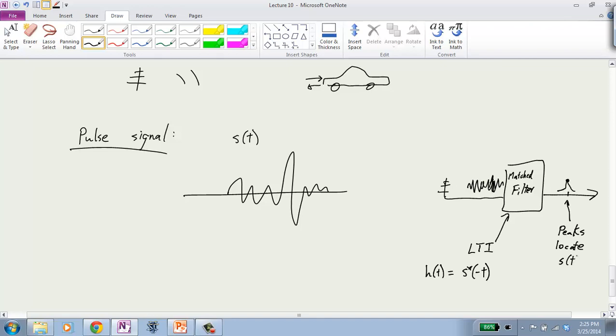So I kind of rushed through this, partly because I told you I'm not going to spend a lot of time on this. We need to move on to other things. But we talked a couple weeks ago, very briefly, about the autocorrelation function. We said that if you convolve X with its time reversal conjugate, that's called the autocorrelation function. And you'll notice that that's what's happening here.